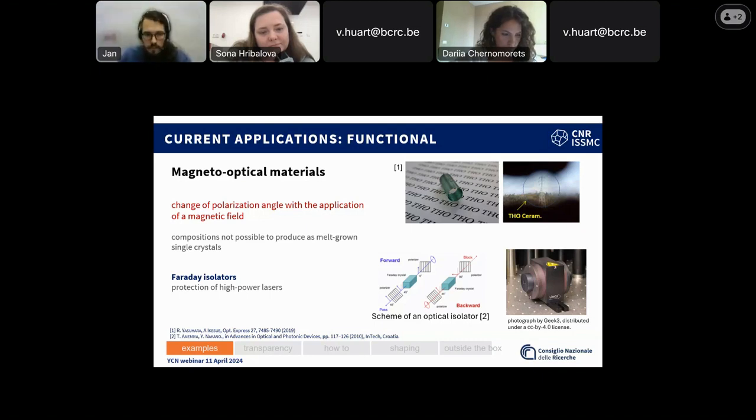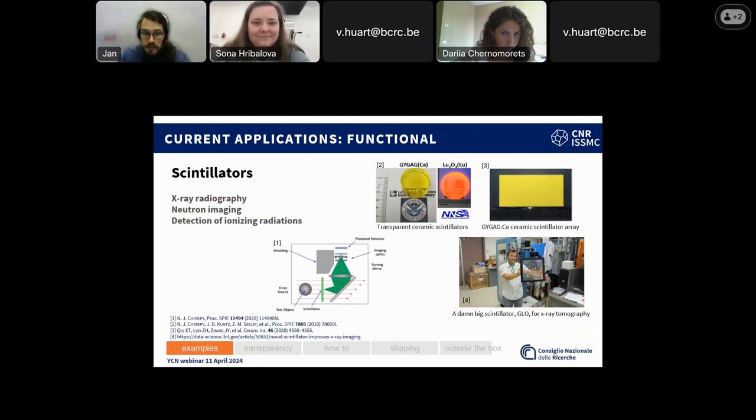And I might start also seeing secondary phases. That means here the process was vacuum sintering. If you use different process, the optimum would be somewhere else. But there are ways to make your material transparent if it can be transparent in terms of, okay, not absorbing, not reflecting.